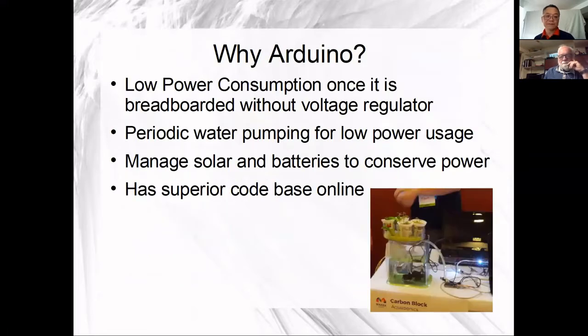So why Arduino? Basically, I did look at 8-bit microcontrollers because I originally thought, oh, they'll be lower power consumption because they're only 8-bit. But I found that the code base for them wasn't as mature as the Arduino. There's lots of examples of Arduino online. I could figure out how to put the processor into sleep mode and have it wake up every 8 seconds and then do the periodic water pumping.